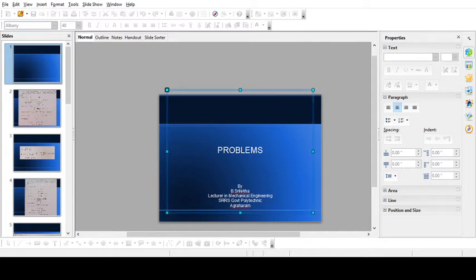So given that area of the cross section is pi by 4 into D square minus d square, since it is a hollow steel tube. So capital D is 18 mm and small d is 12 mm.